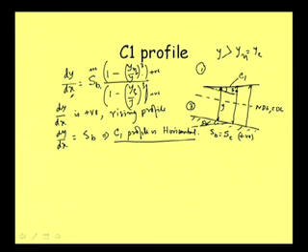So that is what the C1 profile is, and at upstream, of course, we can see that it will meet both the NDL and CDL lines, so at upstream y becomes equal to yn as well as yc, but that ratio is again equal. Whatever may be the situation at upstream and downstream, this ratio is equal, and that is why this profile is always moving horizontally, and at upstream it is meeting the NDL and CDL.